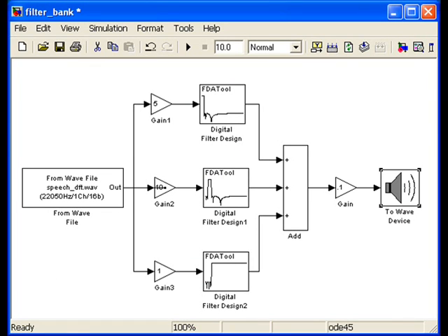The filter bank demo works like this. A pre-recorded audio file is read from the host and transferred to the application running on the DSP. Some computation, filtering, takes place and then the resulting audio file is sent back to the host and played via the speaker. To save time, the Simulink model was generated and it is assumed that users are familiar with Simulink.